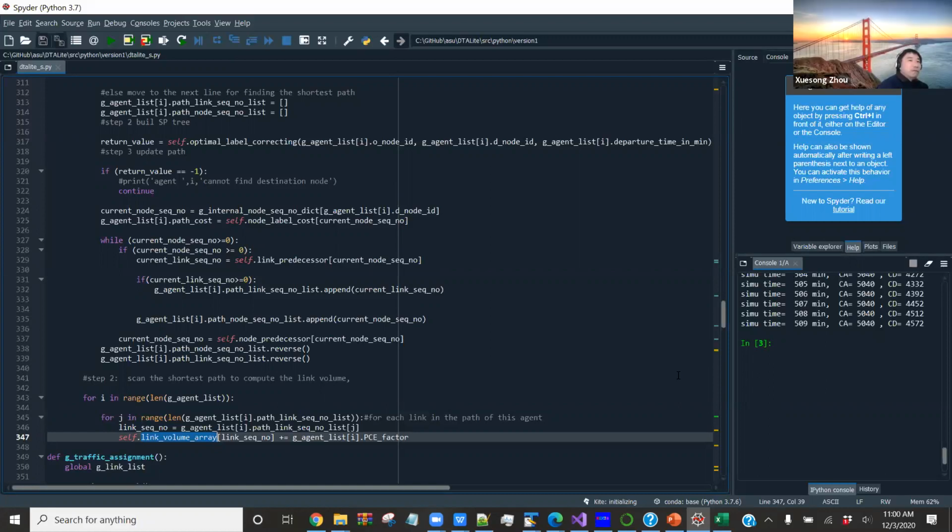The objective: for iteration 0, the first iteration, we are using the shortest distance, or I will say the shortest distance divided by the free flow travel time. So we are using the free flow travel time. Once all the agents are using the likely shortest path, we become congested. We have the feedback loop, do the BPR to propagate. And then we are going to do this iteratively, typically for 20 iterations to reach the user equilibrium.